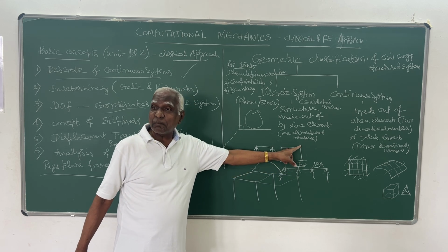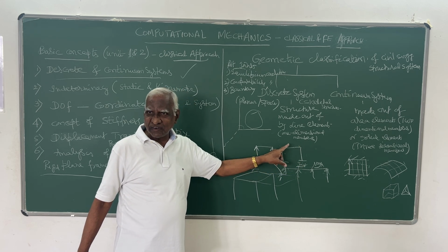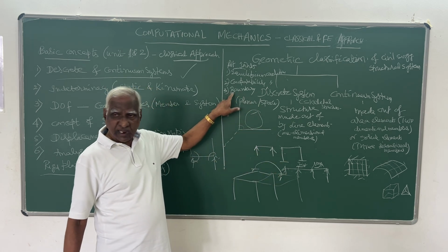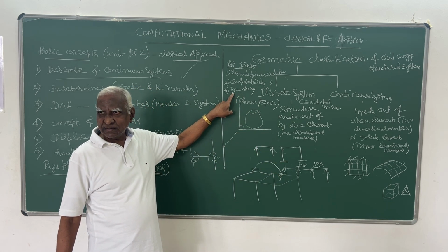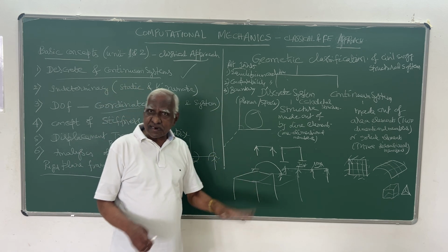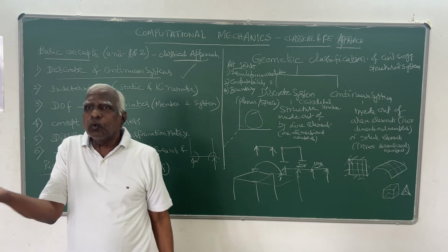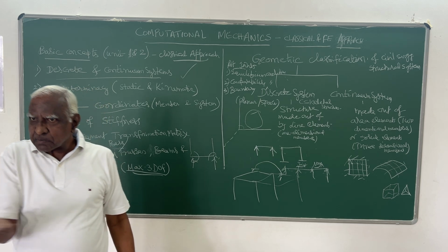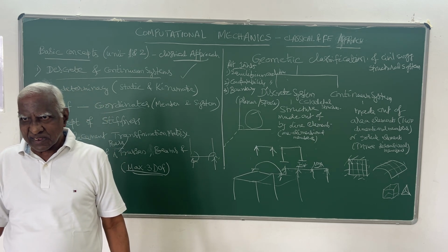Here you don't have a support. It's only a joint, right? So only at the support it has to satisfy boundary conditions. That is, at fixed support there should not be any movement, right? So that is, displacement, horizontal displacement is 0.